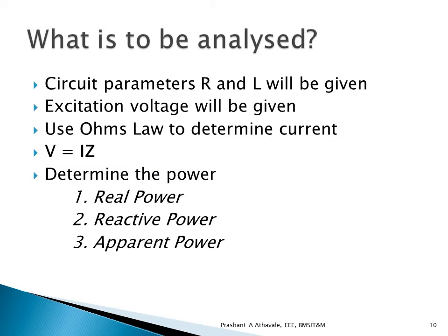So it is very much essential that you know the relation between each of these components very well. For example, what is the relation between frequency and inductive reactance? So you know that XL is equal to 2 pi FL. So if you are given the frequency and the inductance, you will be able to definitely determine the inductive reactance. So if you are given inductive reactance and inductance, maybe you will be able to determine the frequency and so on. So interrelation you should be knowing very thoroughly.